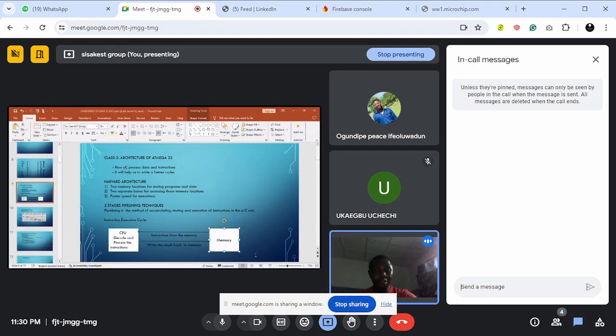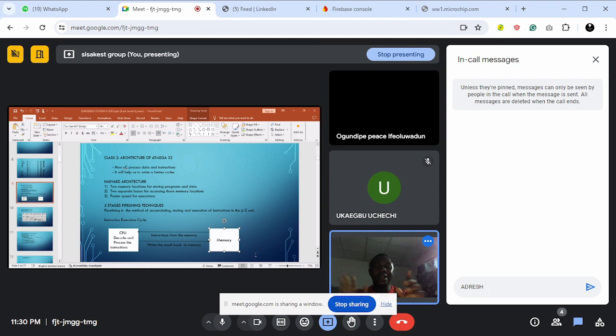If we are talking about the PIC microcontroller, we are looking at two microcontrollers in this class, the result is stored in two registers, ADRESH and ADRESL. ADRES stands for analog to digital conversion result registers.